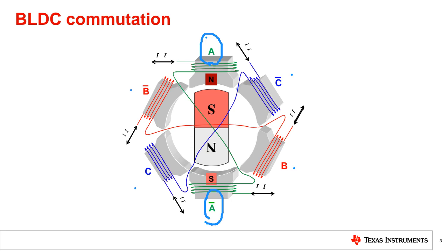The changing of which phase stator coils are injected with current, or commutation, generates a moving magnetic field that continues to direct the rotor along the circle. For example, in A, you inject current, and A moves. Then C dot, one movement. B, one movement. A dot, one movement. C dot, one movement more. This is one revolution cycle.